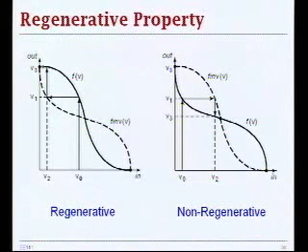So you may have a gate at stage I that has certain noise that gets propagated to the output of that gate, and then you have an additional noise source at the output of the gate that gets propagated through the chain of gates. And the gate will always recover to a fixed voltage level 0 or 1 if it possesses the regenerative property.